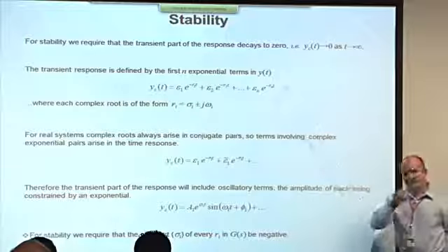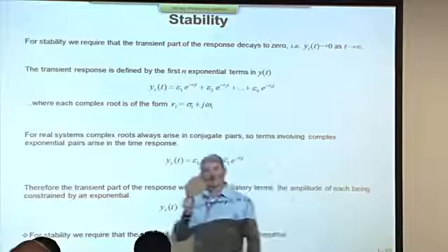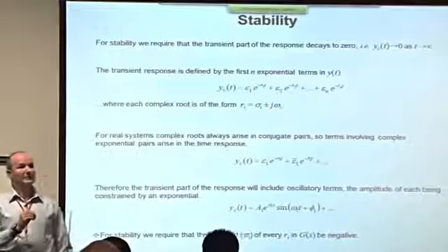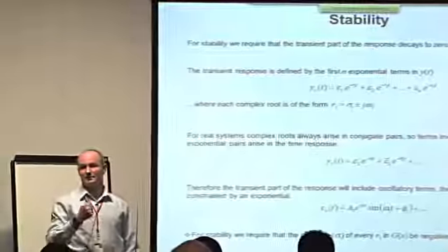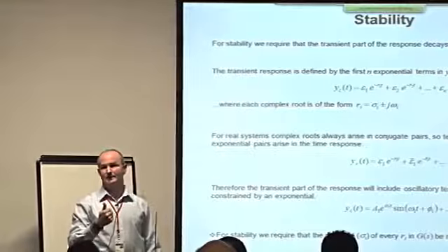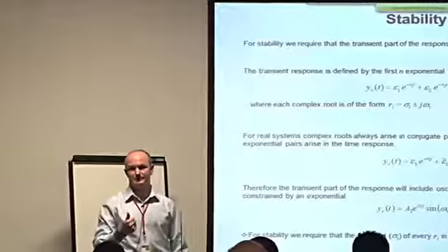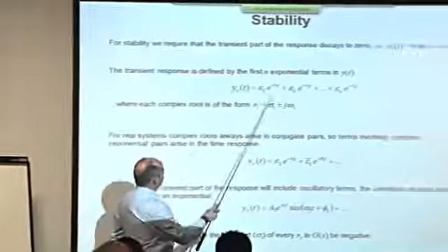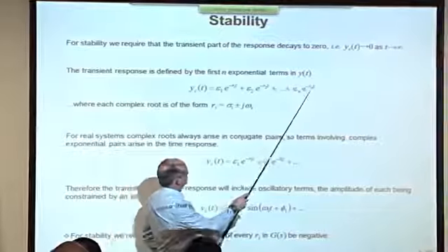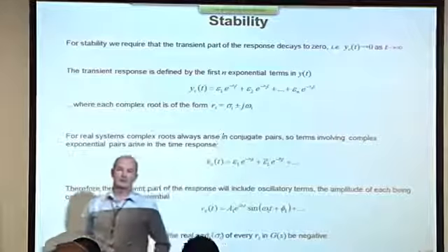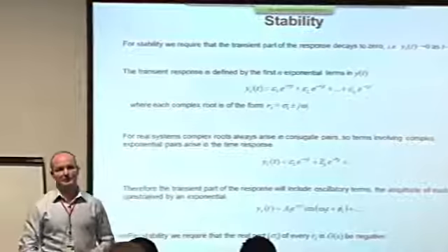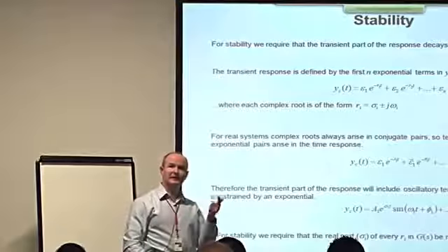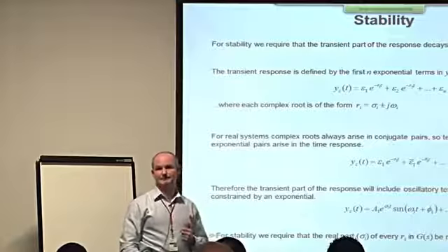Now, remember before when I said that the coefficients in that differential equation, if it's a physical system model that we're using, must all be real. They may not be constant, but they must all be real. And here's the thing about that: when you take the poles, you find out where these poles are, because those coefficients were real, there's only two possibilities for those poles. They'll either be real, or if they're complex, they'll exist in complex conjugate pairs.